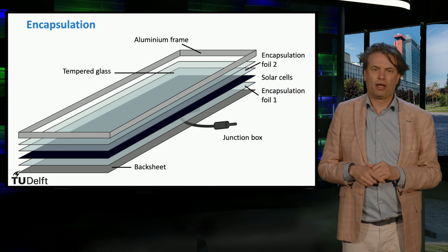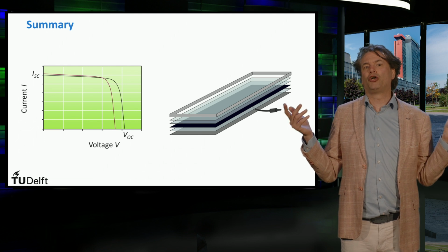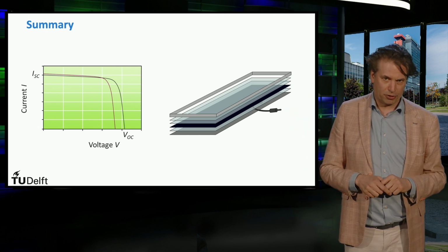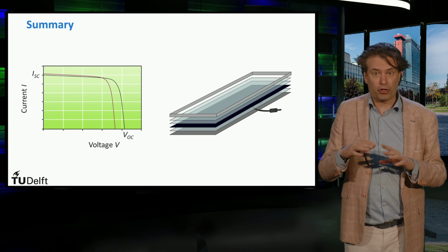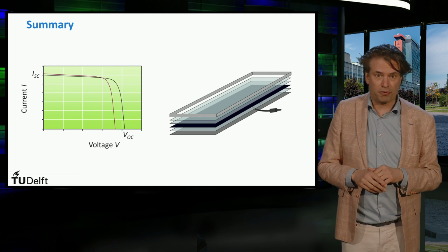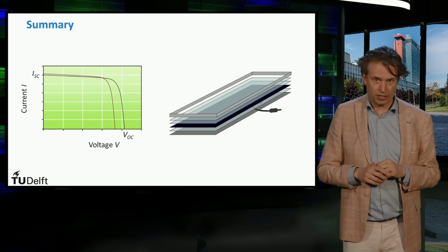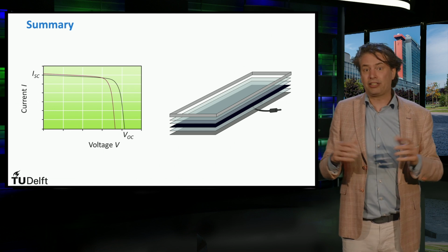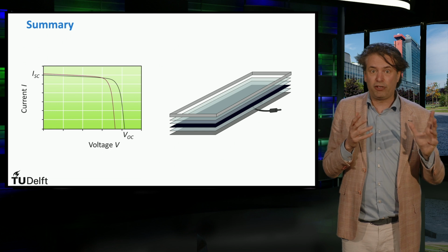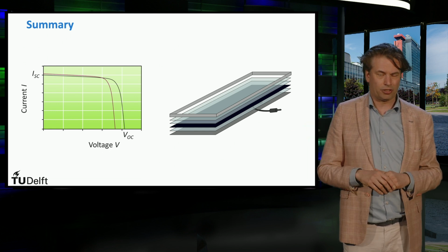Let's recap. The performance of a PV module shows a dependence on the module temperature. Open circuit voltage and power outputs show a small reduction with increasing temperature, while the PV module's current shows an even more subtle increase with increasing module temperature. We have discussed how to calculate the external parameters of a PV module at a given module temperature in reference to the standard test conditions.